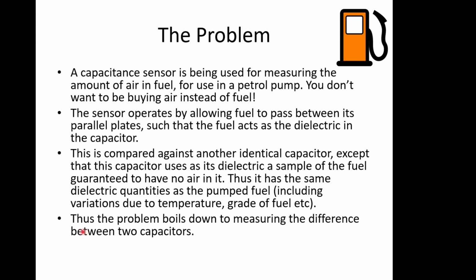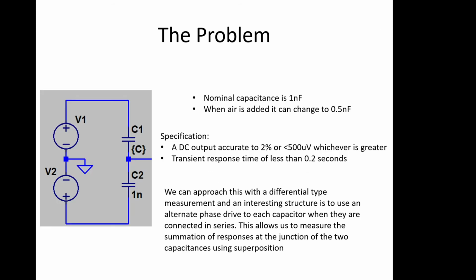So the problem really boils down to measuring the difference between two capacitors, one which is relatively fixed and one which you hope is fixed, because it'll have fuel in it, but if it has air in it, it'll be very different. And so really, we're looking at two capacitances. We need to measure what's going on.